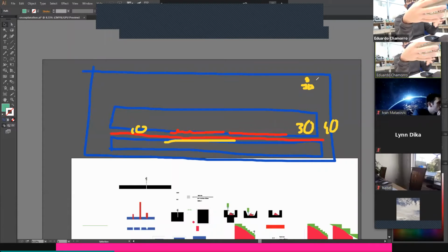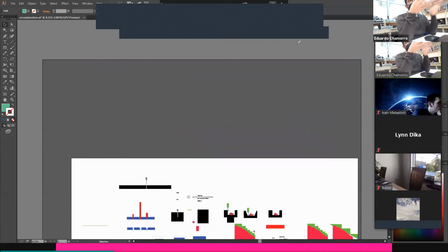Everything depends on geometry, also on the speeds of cutting and the material you're cutting. I know it's annoying, that's the annoying part of the CNC. Everything is variable, a lot. You have a really safe margin area that you can work with no problem: 5, 10, like 10 millimeters, 20 millimeters. Yes, you waste material, but we stay on the safe side. We can cut slower, at slower RPMs. Yes, we give more room to play with the margin.